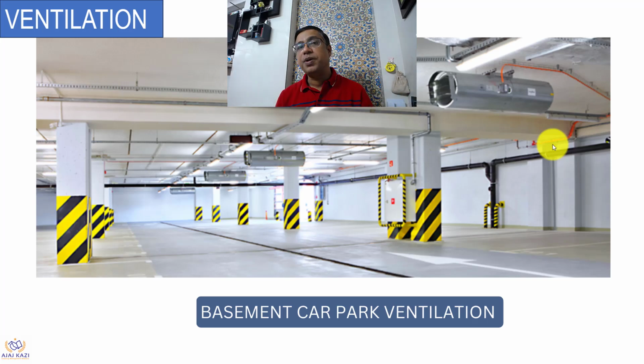If you have a huge basement, it is divided into multiple zones. According to zones, you make your systems zone by zone, right? Rather than having one fan for the entire basement and spreading the entire smoke everywhere. So you have a proper scheme developed, and the scheme has to be tested and commissioned, so that the purpose for which it was designed is seen on the ground. You need to do the testing. So these are the basement car park ventilation fans.